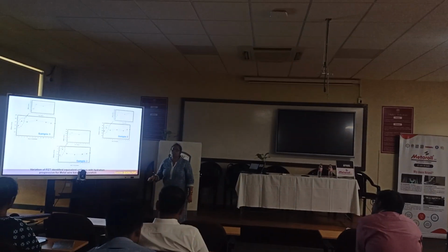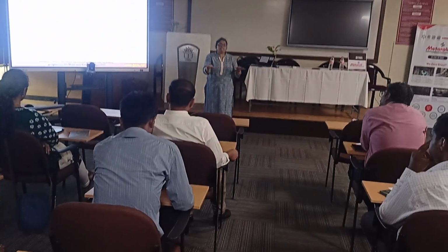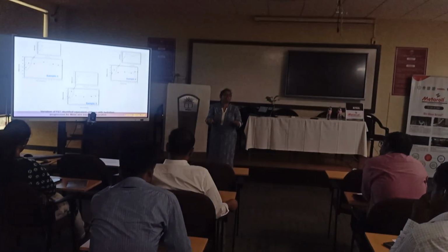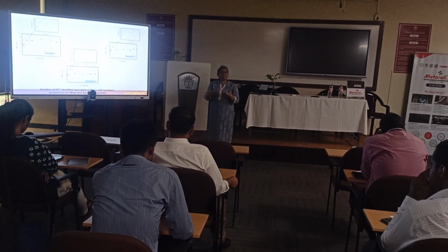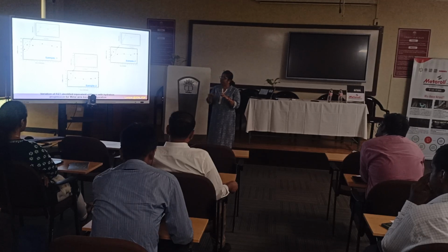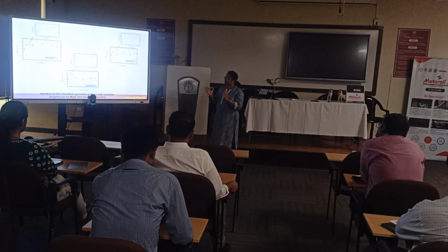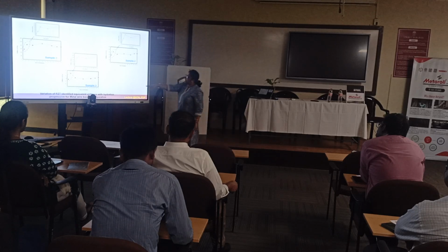But later on, from the 3rd to 7th day, there is what is called a stagnation phase. The stagnation phase is where you get solid state hydration. The water is supersaturated, you don't have any water to react with the cement particles. The saturation has already happened. All you have is the crystallized compounds, and they react among themselves to form the strength compounds.